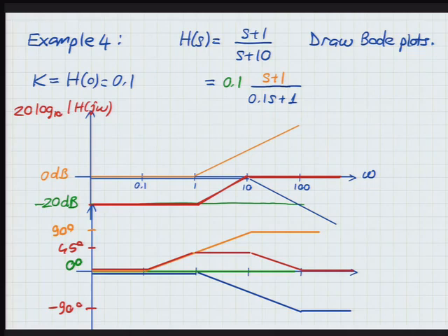Okay, so the phase goes up and comes down. And the magnitude starts at negative 20 dBs, goes to 0 dBs. In the linear scale, negative 20 dB means 0.1, right? So that means the magnitude started at 0.1, went to 10. No, went to 1, 0.1 to 1, right? Because 1 is 0 dB. And the phase started at 0, went to 45, and came back.